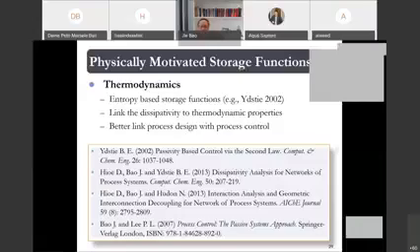Our current work is pretty much using machine learning tools to determine, for example, the dissipative properties of the data trajectories, and then use that to determine the stability constraints we should have in data-based control, particularly data predictive control, very much like model predictive control, but based on data, not on the model.